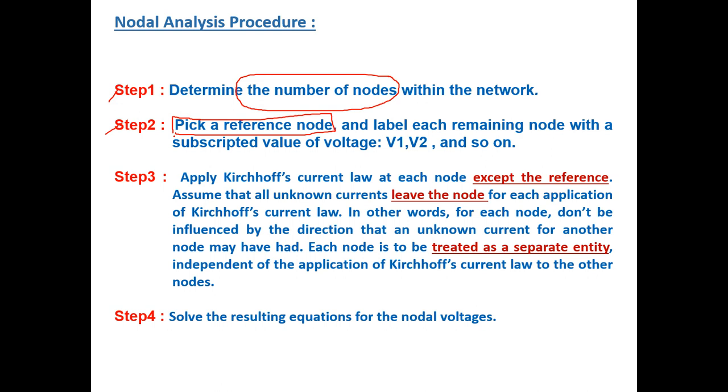We will tell you how to pick a reference node. Step number 3, you apply Kirchhoff's Current Law, which is KCL, for all the nodes, so at each node except the reference node.